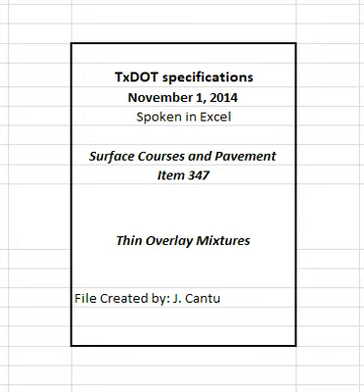5.1.1 Target percentage. The JMF target asphalt percentage will be used to calculate the weight of asphalt binder unless the measured asphalt binder percentage is more than 0.3 percentage points below the JMF target asphalt percentage or less than the minimum percentage specified in Table 6. Volumetric meter readings will be adjusted to 140 degrees Fahrenheit and converted to weight.